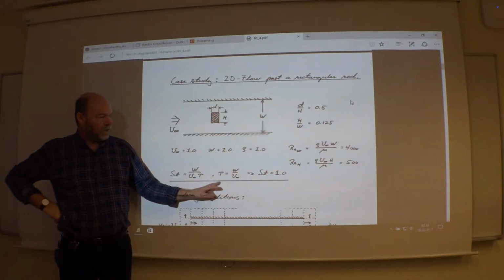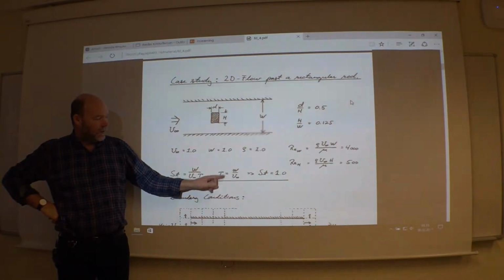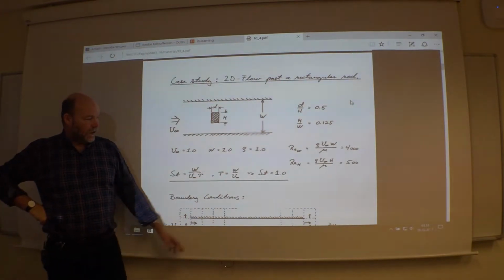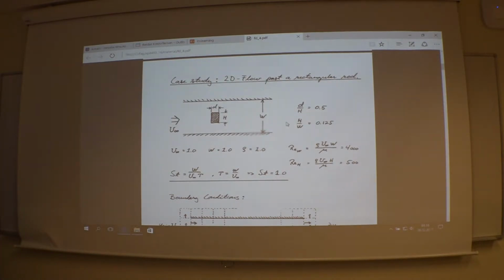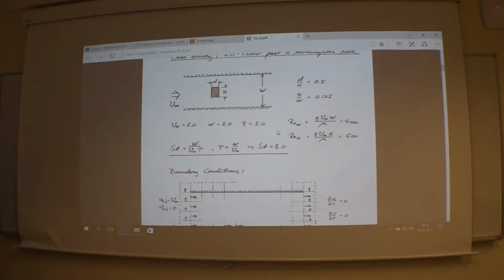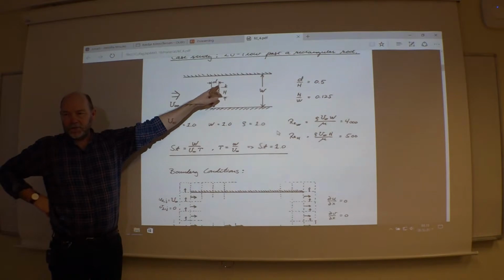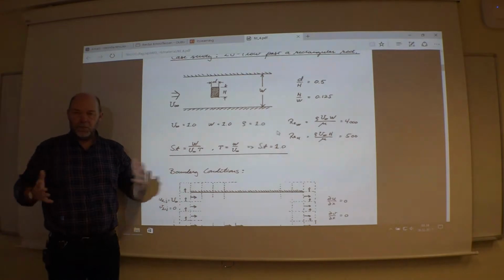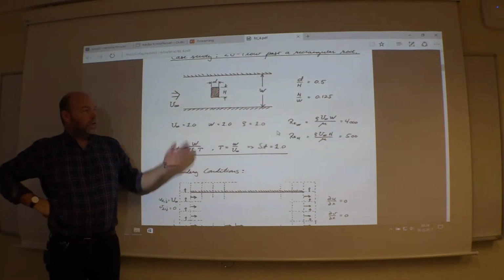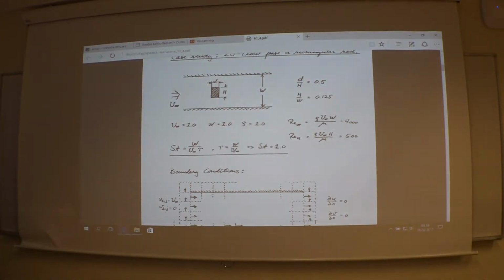So we really have no other choice than create this sort of a dummy default time scale, length by velocity, setting the Strouhal number to be 1. And then Reynolds number is the only parameter into the problem. And then play around with delta t's and hope that we don't skip the entire dynamics entirely. That's the danger. I mean, if you have a fairly big delta t, then you might overrule the dynamics in the problem. So you have to be careful when you don't know this time frequency. So here we are searching for it.